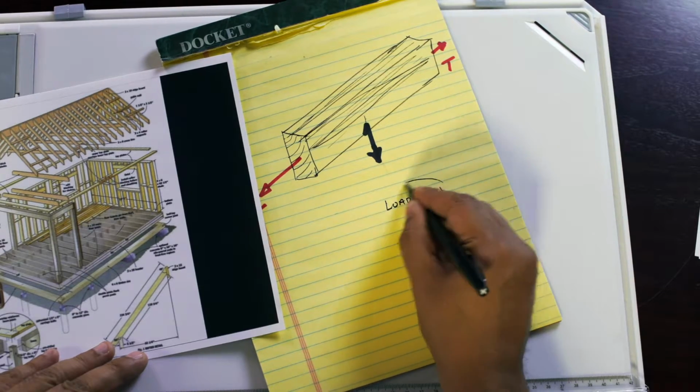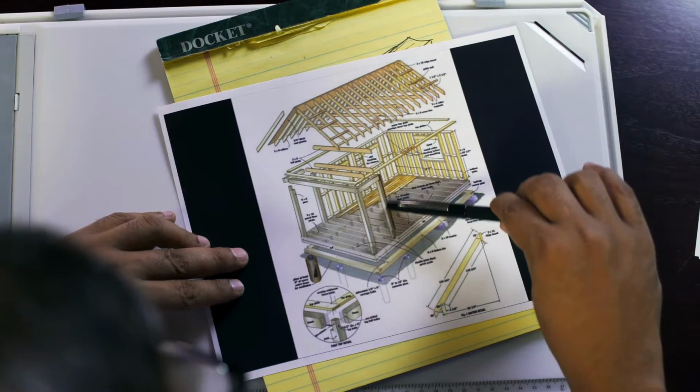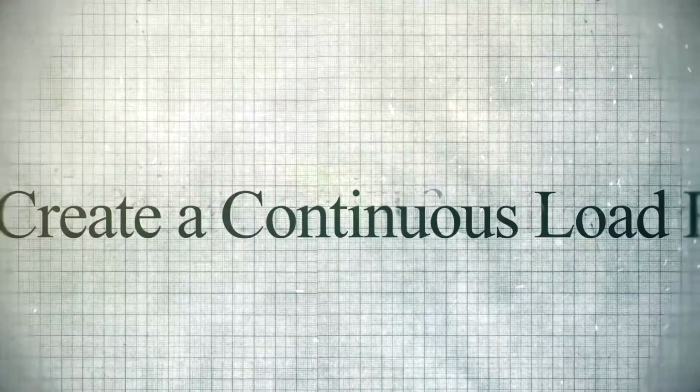And load path is a very important term to understand, because when you design a structure, if you don't have a way for the loads to travel and get down to the footing, then you have a missing link, and that structure is not going to be able to stand up. So architects who come up with fantastic floor plans and spectacular designs, but if we don't have a load path, there's something missing there.